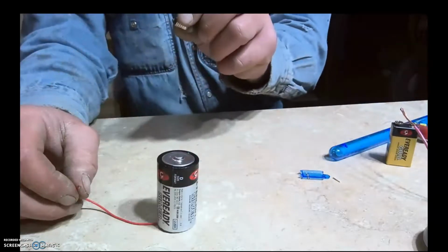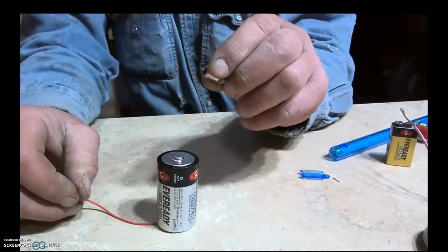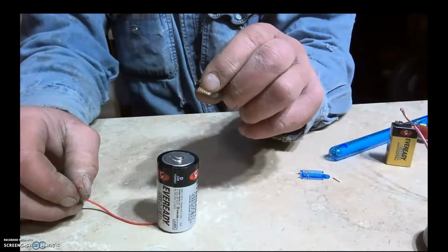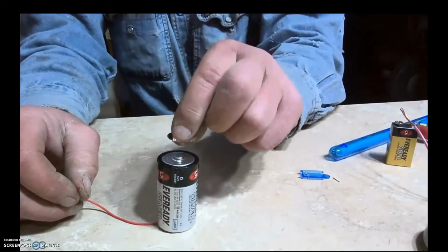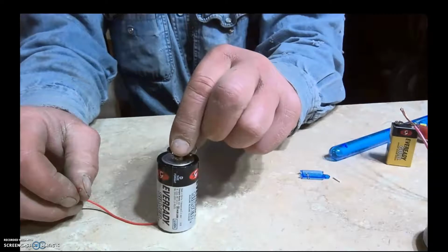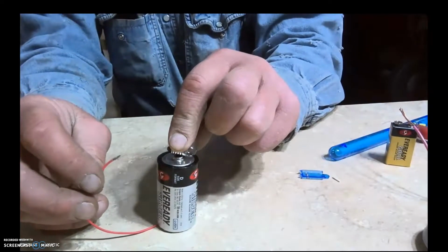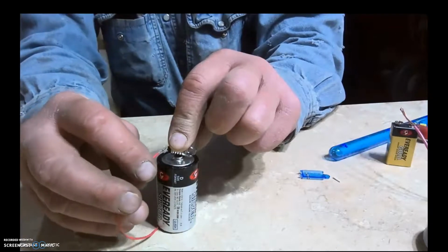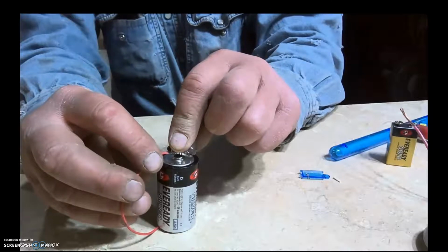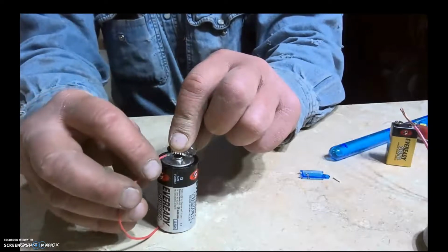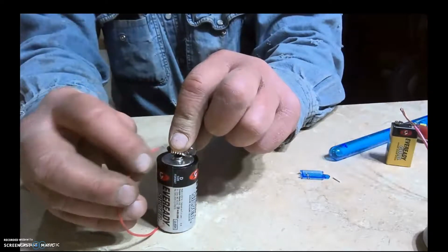So basically, every way that we put this light bulb on this battery will cause it to light, except on the plastic part. No, negative. If you take the screw part of the bulb and put it on the positive terminal of the battery, and then you touch the wire coming from the negative terminal on the battery to the screw cap of the light, it's not going to light, because that is not completing a circuit from the positive terminal to the negative terminal of the battery.